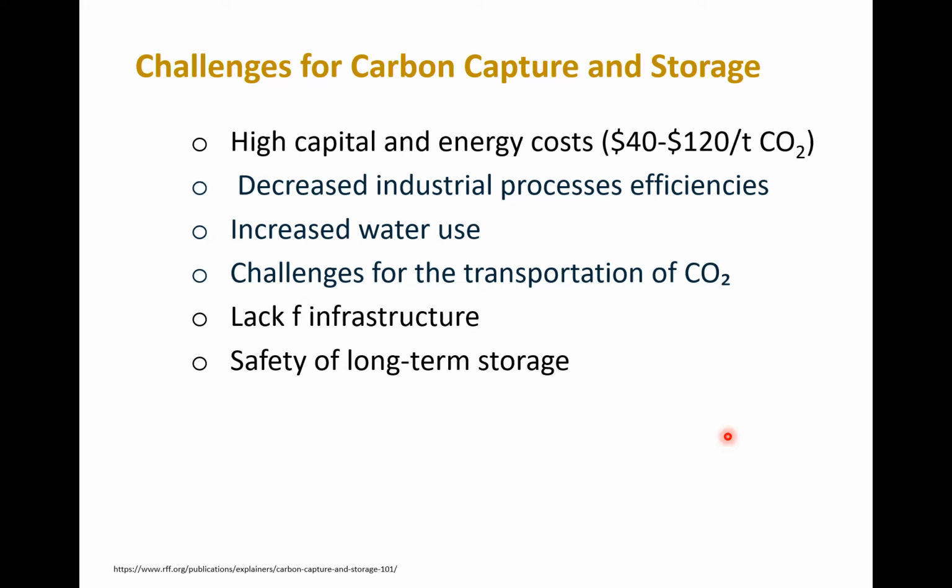Even sometimes, this carbon capturing can be used for capturing carbon dioxide from a fermentation process. As you know, ethanol fermentation can produce carbon dioxide. This carbon dioxide can be recovered, and in this case, the cost will be lower than $40 per ton, because the carbon dioxide in this case has higher concentration, and of course the concentration in the stream is one of the factors affecting the cost of capturing.